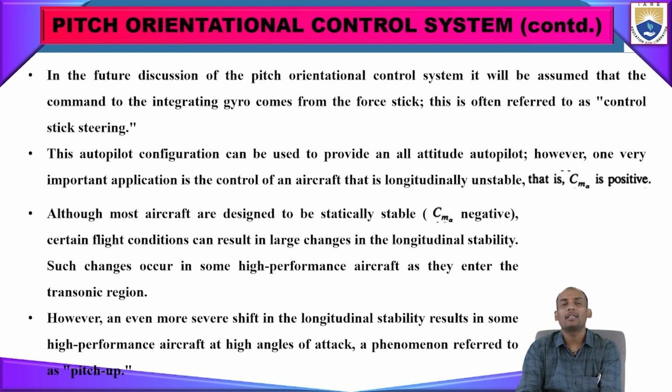So it is operated like control stick steering only. So this autopilot configuration provides attitude autopilot only. However, one important application of this is that longitudinally this operation is unstable. That means CM alpha, the stability derivative CM alpha, is positive.